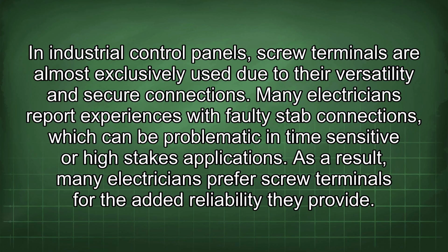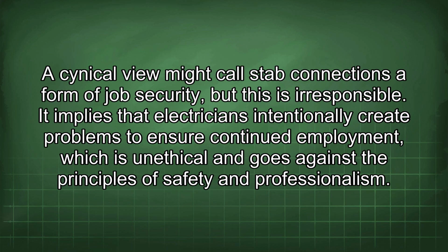Many electricians report experiences with faulty stab connections, which can be problematic in time-sensitive or high-stakes applications. As a result, many electricians prefer screw terminals for the added reliability they provide. A cynical view might call stab connections a form of job security, but this is irresponsible. It implies that electricians intentionally create problems to ensure continued employment, which is unethical and goes against the principles of